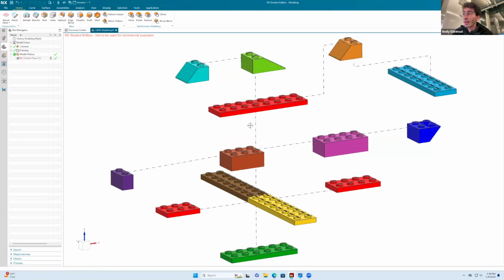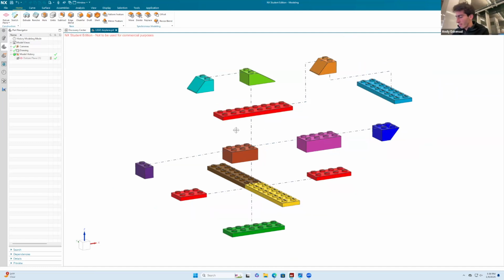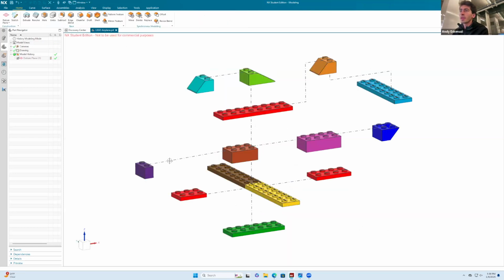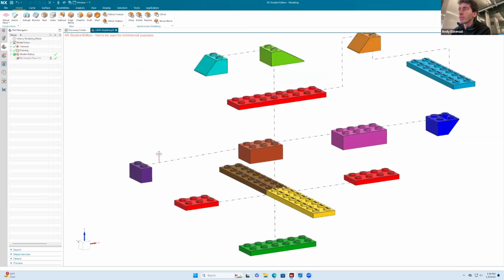I was just trying to figure out how to come back here to the assembly mode. It was just Control M. And if you go back here to Tools, Application Drafting, it takes us back to where we were. So I'm gonna go back here to Control M to figure out what was going on with this line in here.